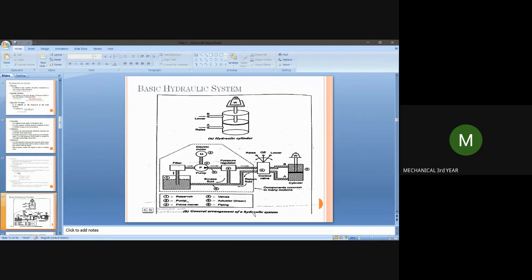The pump is a very precision instrument. If we do not use the filter, these solid particles enter the pump and damage it. The pump is the costliest component in this topic, so it has to be properly maintained. In order to remove all those solid materials and dust particles, we deal with the oil using a filter, and once the oil is free from dust particles, it is sent to the pump.